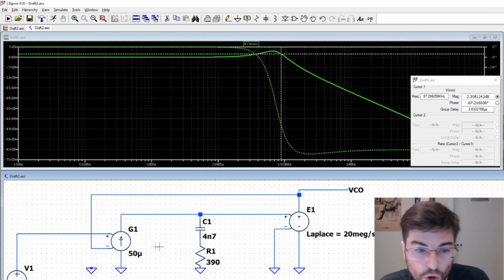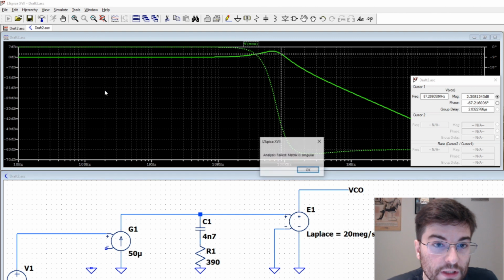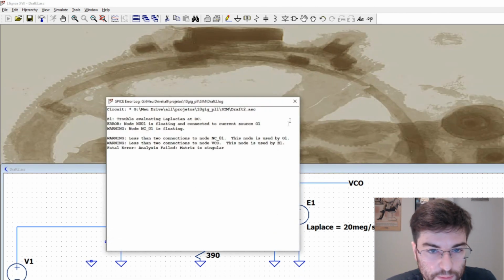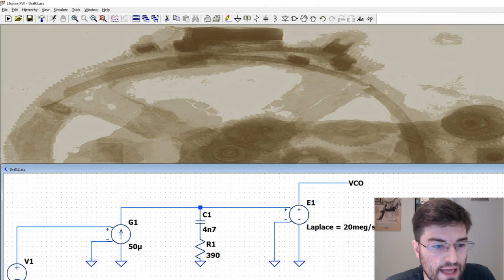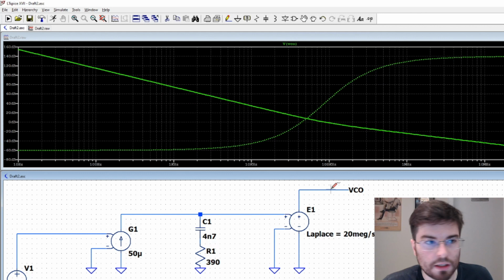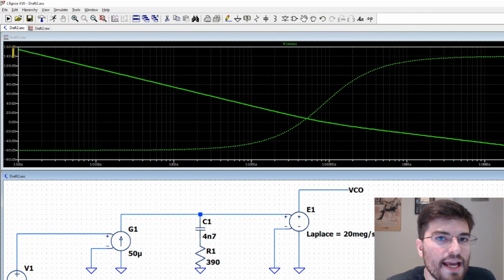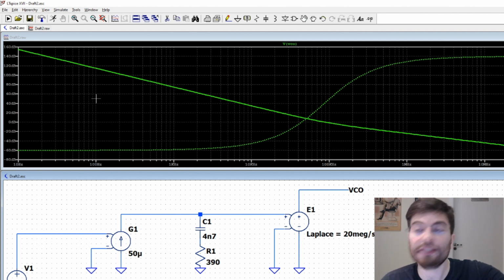You can see that the open loop gain here, for our design using the sampler, is 160 dB, which is pretty large. So I designed a pretty low gain charge pump here to attenuate a little this pretty high gain.